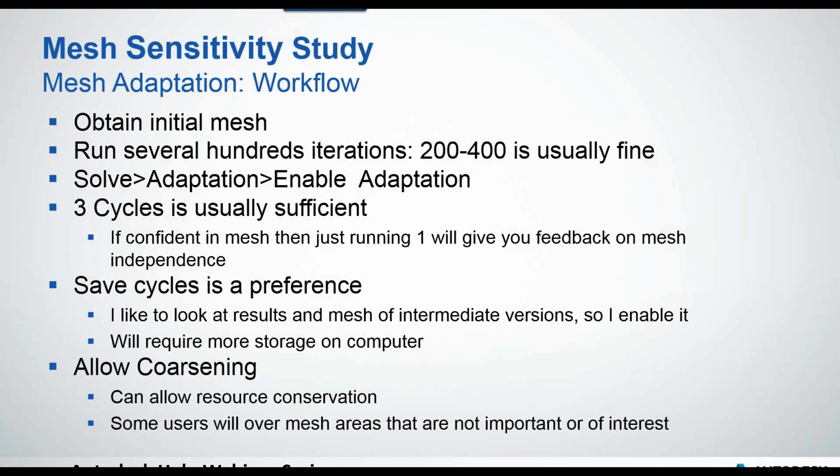And then there's also an option to allow coarsening. So maybe you overmesh some areas. CFD is a time-consuming process, so why not allow coarsening where it could be done without sacrificing results?